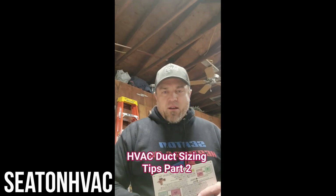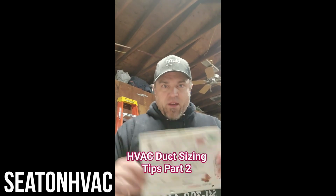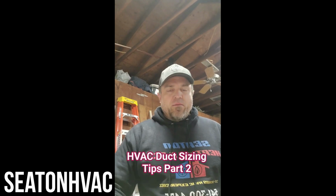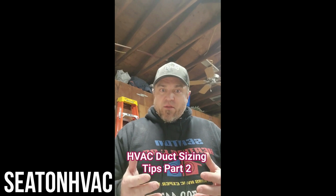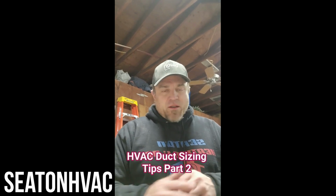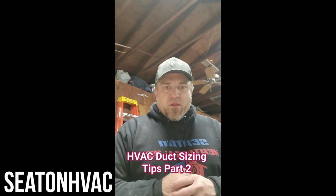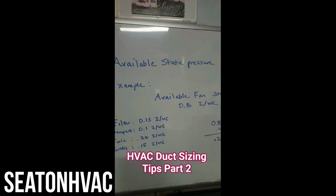All right, guys, Seton HVAC here. So in step 1, I told you that the first step in trying to figure out what our friction rate is going to be on our ductulator is finding out what our available static pressure is. So how do we do that? Well, let me show you an example. We've got to find this number out first, otherwise that ductulator is worthless to you. So let's head over to the whiteboard.